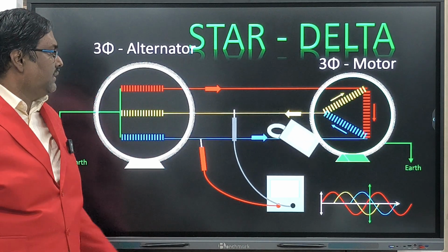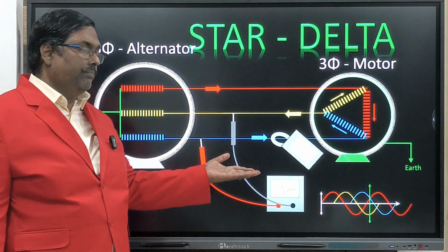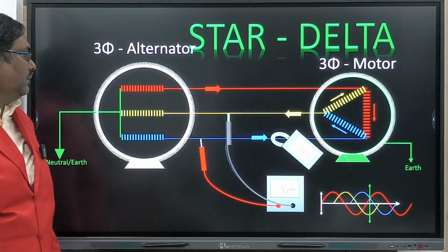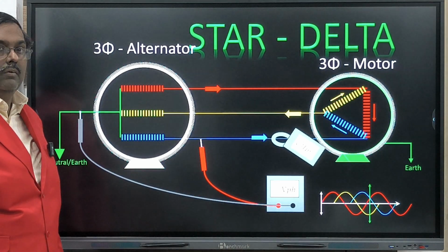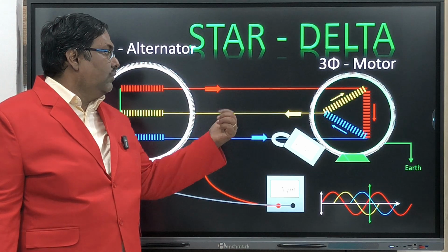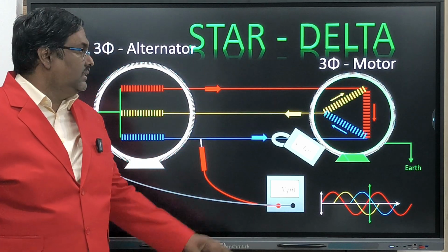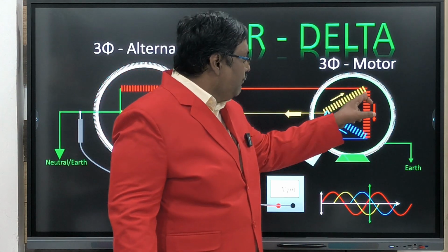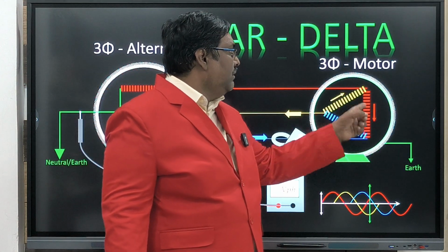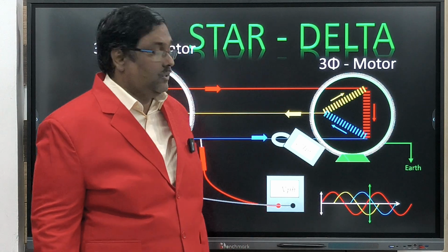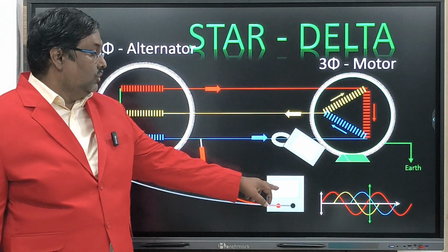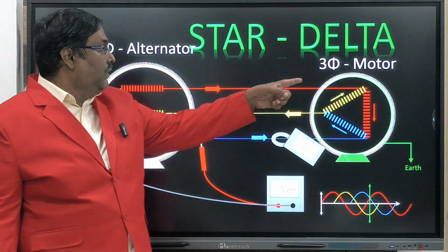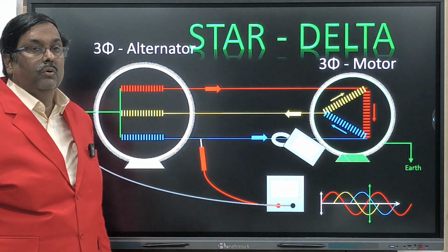Okay. So you can measure all lines, similar, same. And if you measure here the phase voltage, you will get the same, no difference. See? This is the phase voltage and the line voltage. What I told you, this line voltage is passing through here, crossing the coil ends. That is called phase voltage. That is why I mentioned here. Okay, so this is 440, not this volt. This is a single phase volt. This one is 440. Don't get confused.